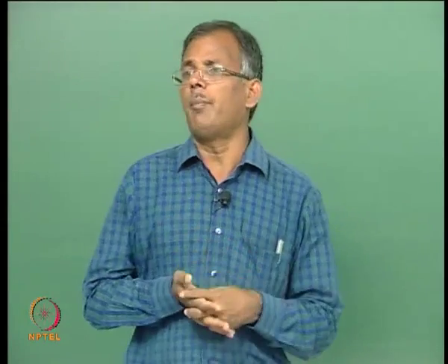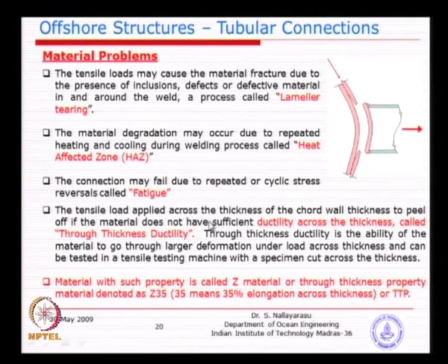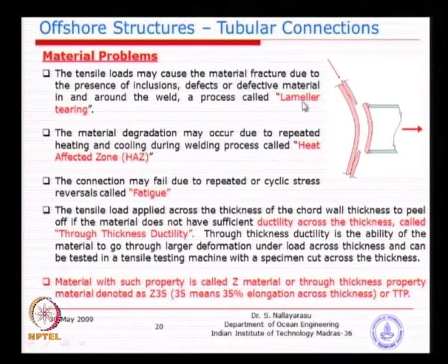So, that is exactly the bonding required between the grain structure, and this can happen in any material, and specifically for steel it may happen when the thickness is larger and larger. For example, with 10 mm there is less susceptibility to coming out, whereas with 50 mm the chance of peeling off is more, and that we call lamellar tearing. Basically the plate comes out in layers, instead of coming out together.